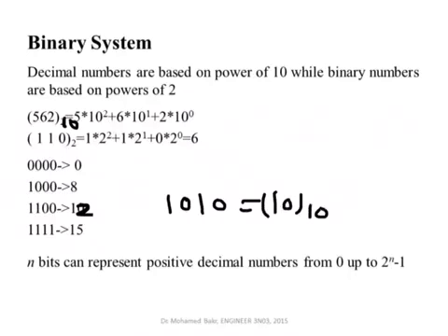So we'll now realize that if you have n bits, we call each one of these binary digits a bit. It can have a value of 0 or a value of 1. A value of 0 we call logic 0. It can be 0 volts, or it can be any low voltage, or even a negative voltage. And we consider the value of 1 to be a high value, logic 1. It can be an actual number, 5 volts or 12 volts, depending on the circuit.